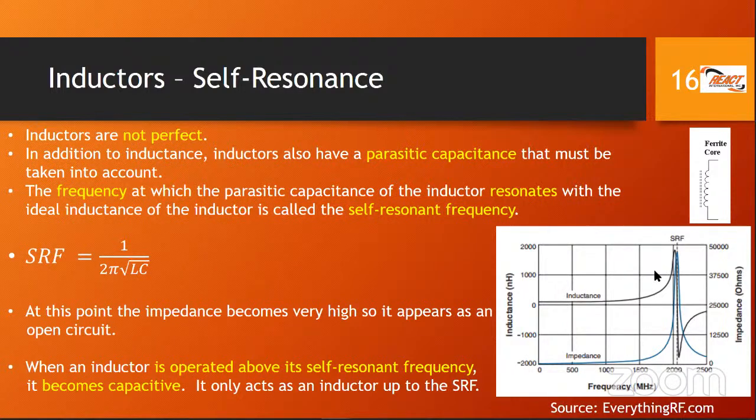But why do we need to know the SRF, or the self-resonant frequency? And remember, the self-resonant frequency takes into account the inductance and the capacitance. It is because when an inductor is operated above the SRF, above the self-resonant frequency, it becomes capacitive. So that is why the SRF is important.